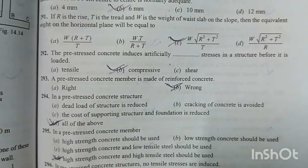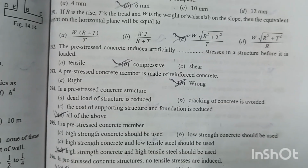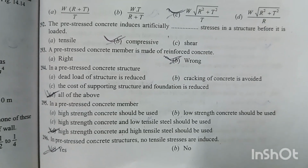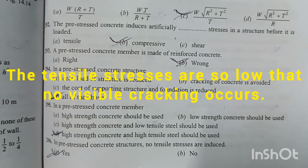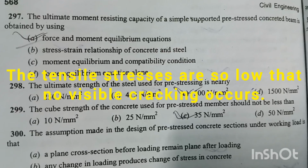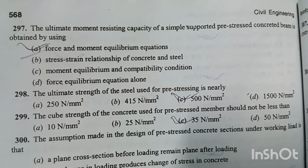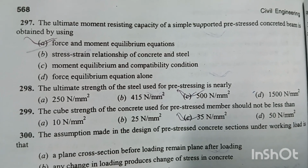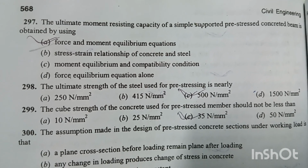Question number 295. In a pre-stressed concrete member, option D is the right answer. High strength concrete and high tensile steel should be used. Question number 296. In pre-stressed concrete structures, no tensile stresses are induced. Option A is the right answer. Correct. Question number 297. The ultimate moment resisting capacity of a simply supported pre-stressed concrete beam is obtained by using. Option B is right answer. Stress strain relationship of concrete and steel.